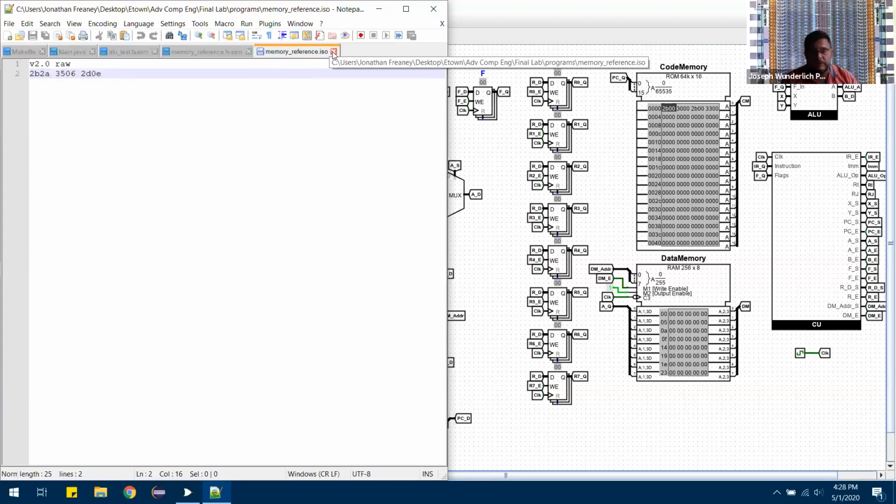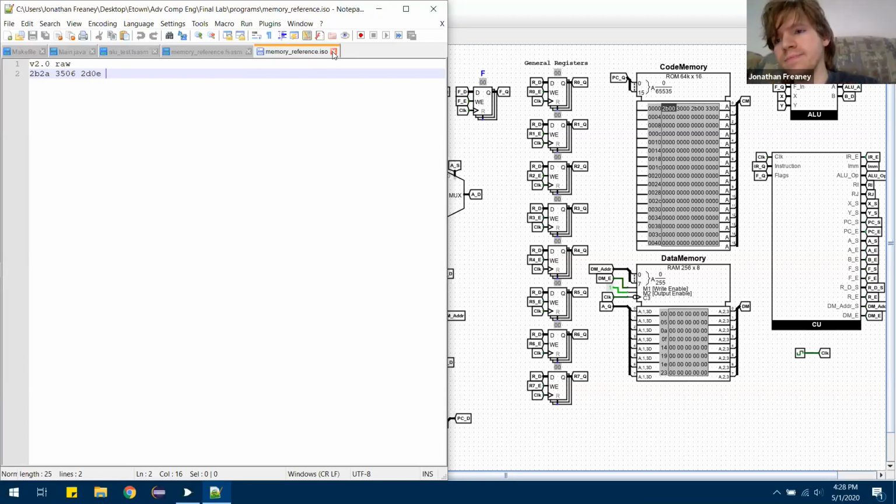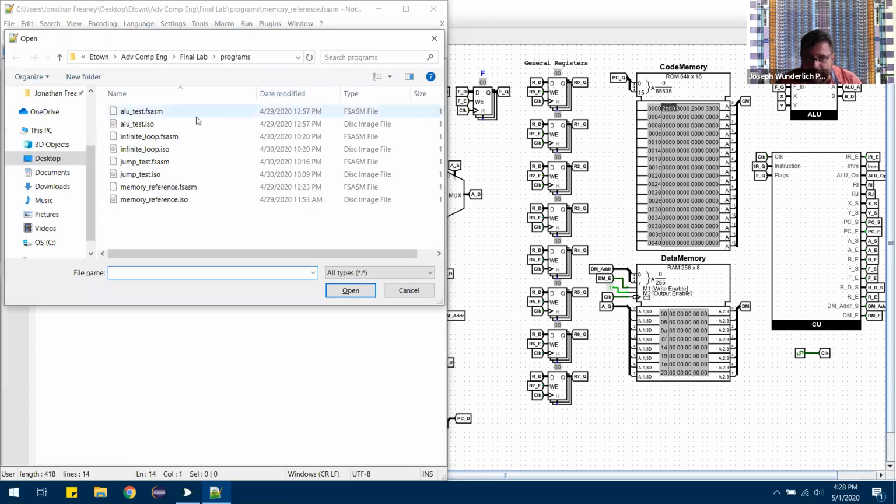Yeah, and the memory reference would even need more stages in the pipeline, sub-stages really. In practice, we'd need more to do that, because you're running at different clock speeds, with your front side bus and your memory and everything. And plus you gotta do other things, typically error correction, or stabilize your address signals on the address line going across the front side bus to the memory, and know to wait long enough. Then often the RAM will say, okay, now I've got it, I've got something stabilized on the data bus. And then you say, okay, give it to me.